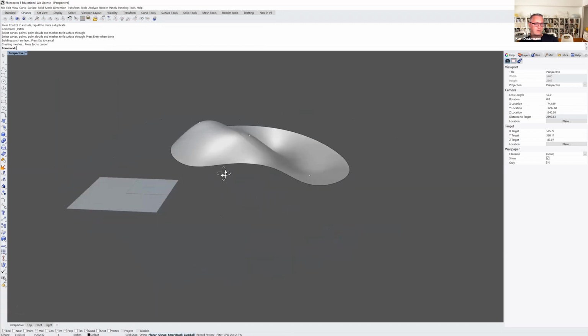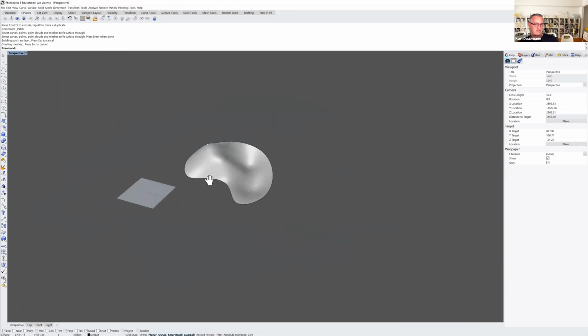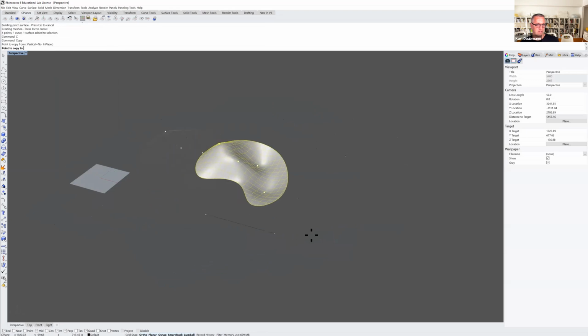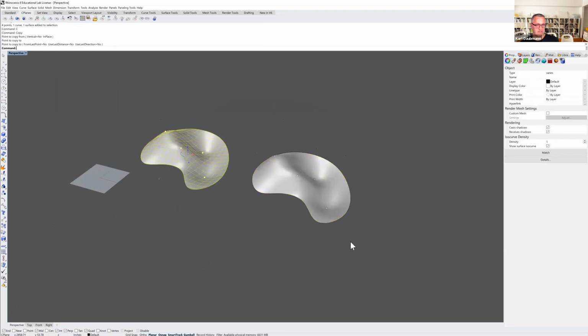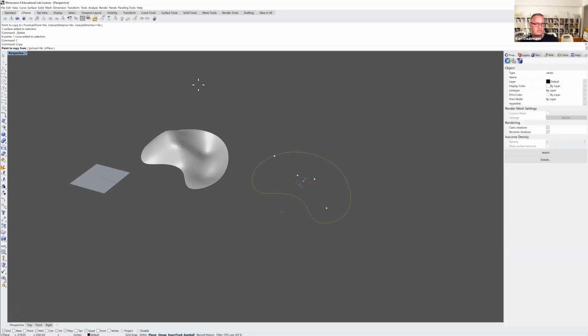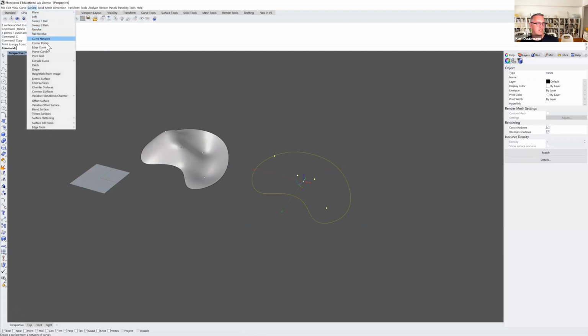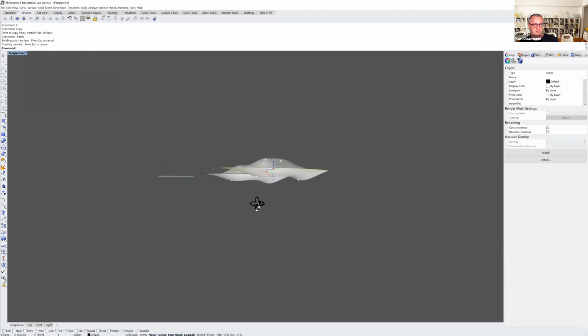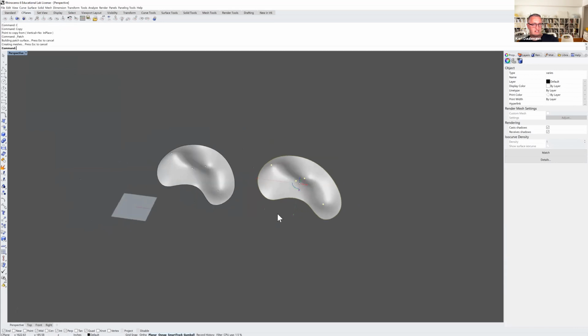And if it's too the opposite of stiff, it maybe can't do that either. And so what I'll do is I'll just, again, keep kind of iterating. I'll delete this surface, but maybe select everything again and make another patch surface. And maybe change now, if I make it more stiff, change it to 1. It seems to still work, okay?